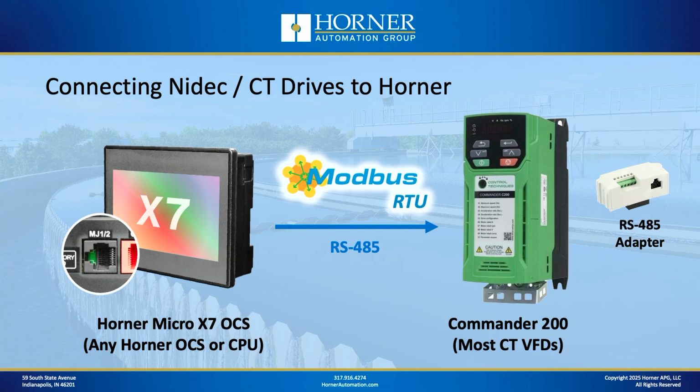Also available from a Modbus perspective is Modbus RTU. That's RS-485 based Modbus. For that, you'll need an RS-485 adapter that you can plug onto your drive. And of course, RS-485 is built right in to the Horner controller. So that's another option, and it happens to be the option we're going to talk about today, with all the details you could need to talk RS-485.